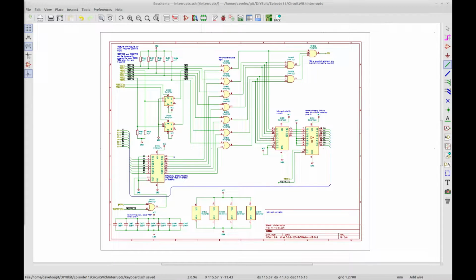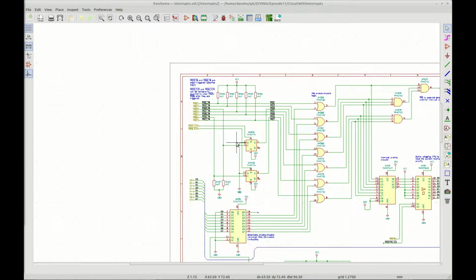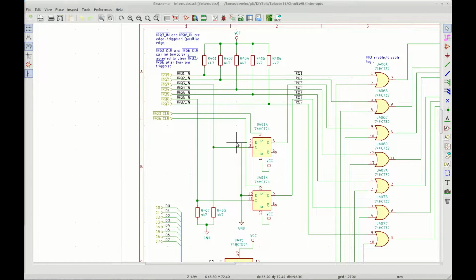Here is a schematic of a design which implements the desired features. The interrupt controller circuit is somewhat complex and is split into several components. The components are inputs and edge detection, the mask register, the mask-unmask logic, the priority encoder, and the CPU IRQ Signal Generator. Let's start by discussing the inputs and edge detection logic.